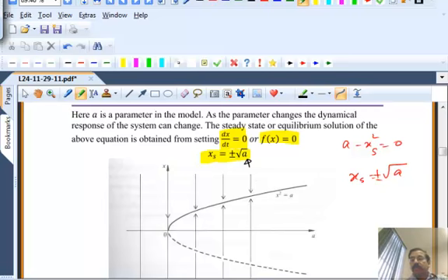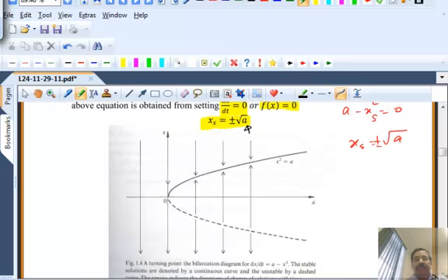No. This kind of diagram is called a bifurcation diagram, which simply says the state x plotted against the parameter a. So in fluid mechanics, it will be the velocity plotted against Reynolds number. What are we interested in answering? Is there a critical Reynolds number above which a particular flow becomes unstable? When it becomes unstable, what happens to it? That is the path towards turbulence. And that's what we are interested in answering.